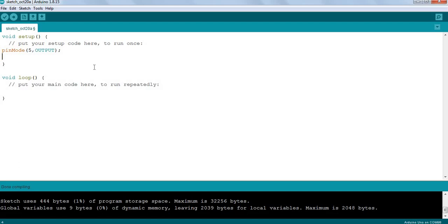So initially the LED will be off and slowly it will glow with increasing brightness. Since the brightness is increasing, the value which we are going to pass is changing. And if there is a changing value, it is always good to use a variable. We can change the value of the variable programmatically, or we can directly make use of the for loop.